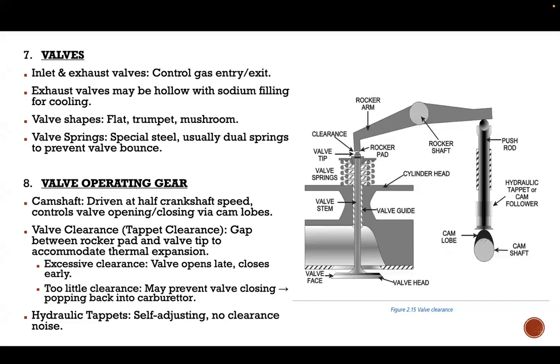If we have a wrong camshaft, or your camshaft is bent, or has gone blunt, your whole engine is not going to work properly, because your valve is not going to open correctly, down or up, which is going to cause us problems. So you have to be aware that you have to have a correctly adjusted camshaft, which is going to help us in opening it.